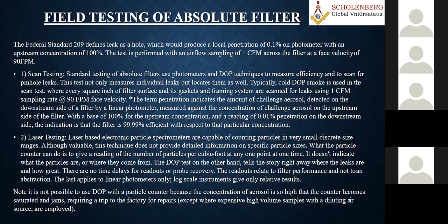And then after that, we also go for the field testing that the federal standard defines. Testing of this absolute filter, HEPA filters, the scan testing, laser testing. Sometimes it is not possible to use a DOP test with a particular counter, because the concentration of the aerosol is so high that the counter becomes saturated, because you have to create a hot spot. So for that purpose only, this type of tests are recommended, in case you are not doing the field testing.